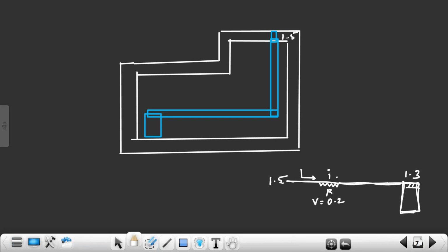So when this 1.5 volt reaches the cell, the voltage would have become 1.2 volts. So 0.3 volt will drop on this metal layer. So it will drop down. This we call IR drop.